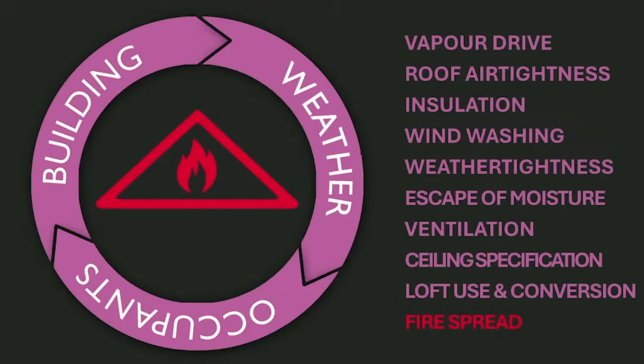AD-B Clause 11.14 acknowledges there is a matter of judgment about whether features such as large runs of dormer windows should be counted as wall sections. Internally, Requirement B3 applies, requiring subdivision of fire-resisting construction between adjoining buildings, and this should extend into the roof space. Such subdivisions should be treated no differently than any other compartment wall. Depending on the building type, ADB2 may require additional separation between parts of a single building with different functions. Again, this requirement extends to the roof spaces above these areas.